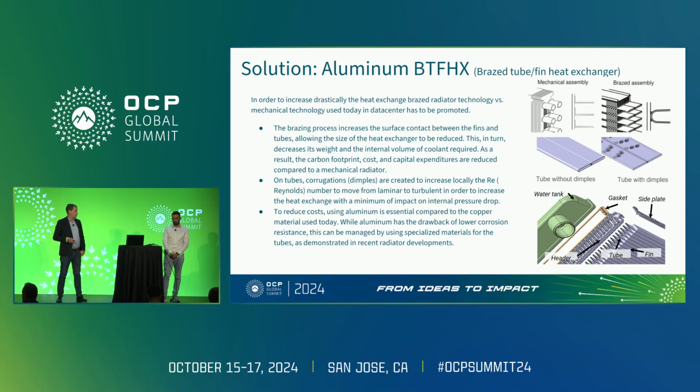You saw in the previous table presented by Mohamad that on internal pressure drop, we have some issues with microchannel tubes, which is not the case with folded tubes. It's really important to have in mind that we are able to manage these issues. And you know better than me that sometimes, with internal pressure drop, we can have at the extreme level some clogging issues, meaning a completely blocked circulation in the tubes.